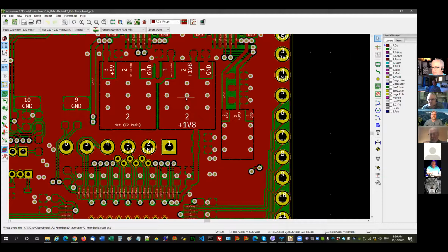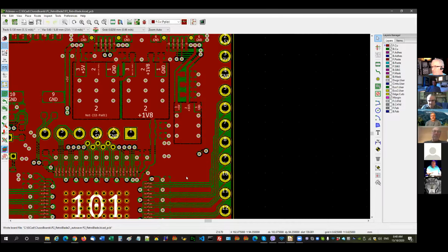The 3.3 volts for the I/O comes through a separate regulator. So I'm not hammering this one. I'm trying to take off the load from this 3.3 regulator. I've got a second one, which is a SOT 89, which is a smaller regulator, still 1 amp, but you're going to use a lot less in the I/O. And it drives the I/O pins for the propeller chip and the flash chip and the USB and the SD.